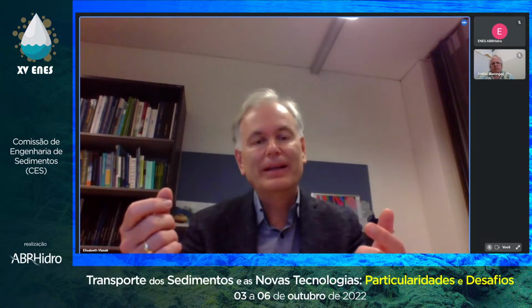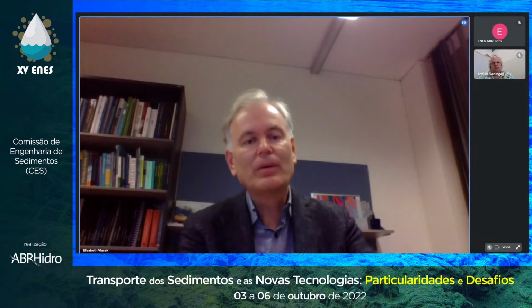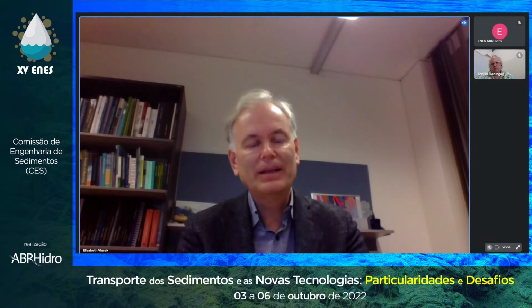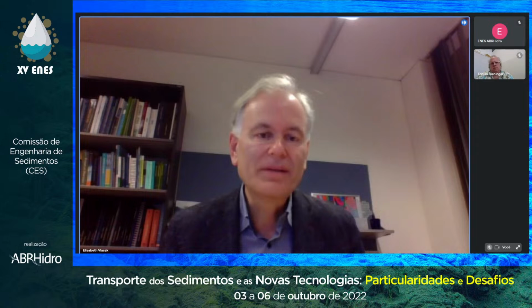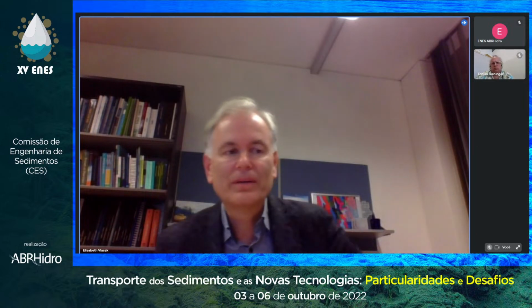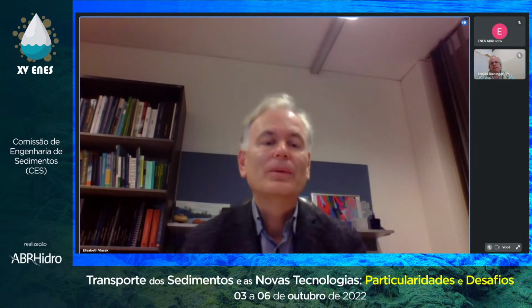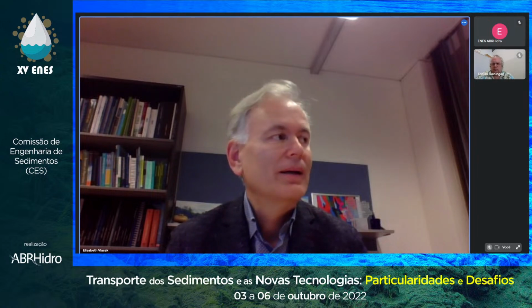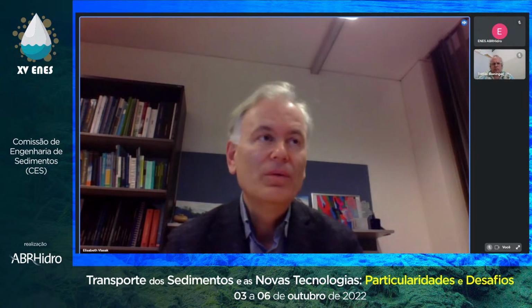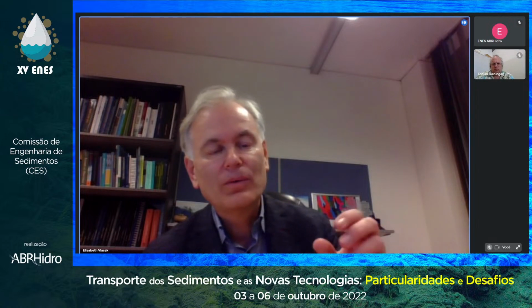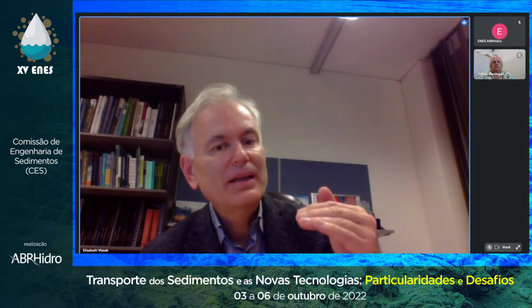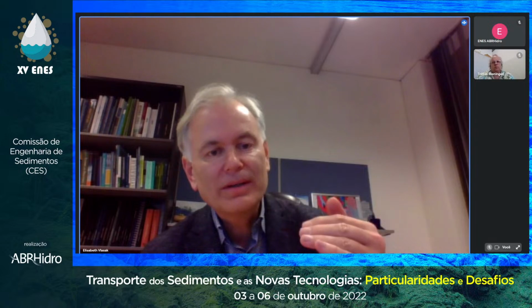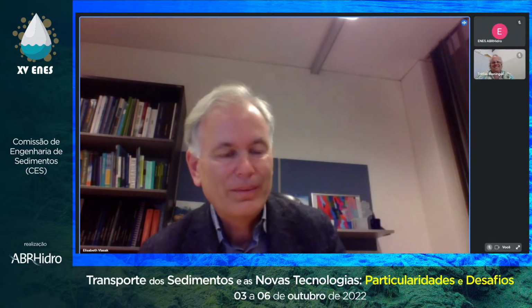So you have to calibrate it. In a way, you go there, you take volumetric core samples. So we take core samples additionally, and do some sort of analysis, for example, what is the specific density. We even use it for kind of a scale model to get the shear stress needed for the erosion, because we know that cohesion is there. So we look into cohesion, and then it makes a difference if you have clay, as you always know.